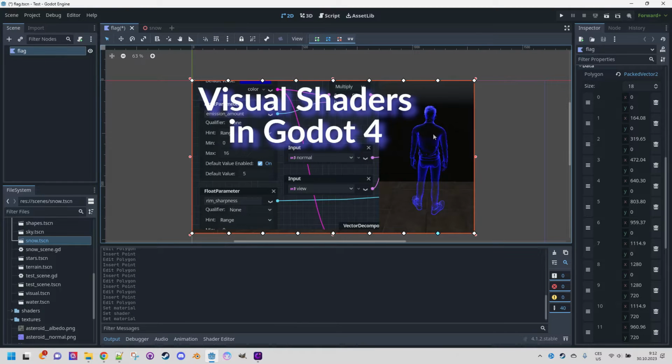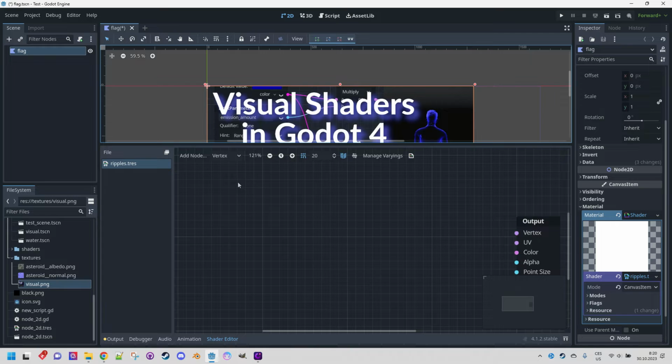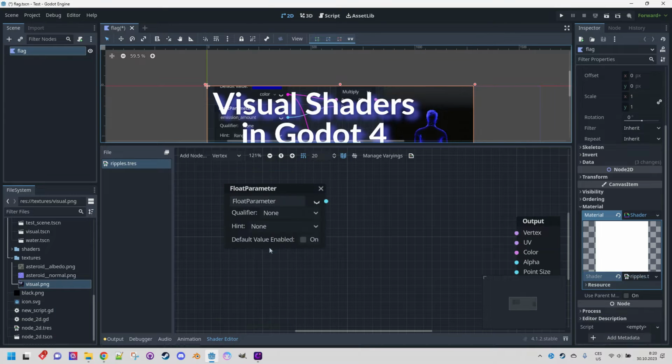The polygon should be ready, so it's time to start working on the shader. I will click the shader property to open the visual shader editor. First, we need to set the input parameters to uniforms. We will have a total of 4. I will start with a speed parameter of the type float because we want to control the speed of the wave effect. Right click and parameter, it would be float parameter.